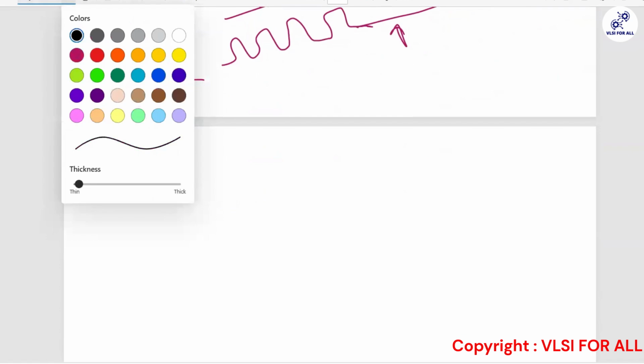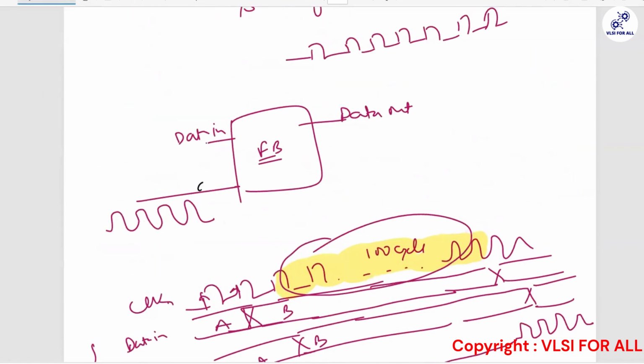So what will happen is, this is the clock going in. The designer will generate an enable signal. Let's say I have applied an AND gate. The clock will go into the AND gate along with this enable signal. So whenever this enable is high, then only the complete clock will go here. Otherwise, we'll send 0 only, because if enable is 0, this clock will be 0.